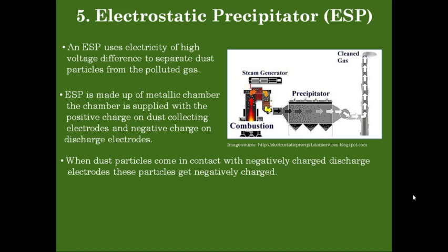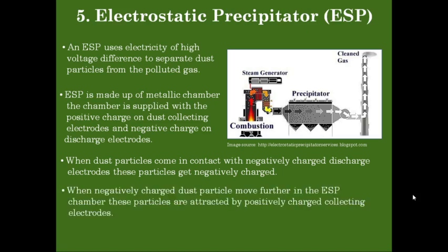Now when these negatively charged dust particles move in the ESP chamber, the chamber is surrounded from both sides by the positively charged collecting electrodes. We know that opposite charges always attract each other, and by this principle, the negatively charged dust particles will get